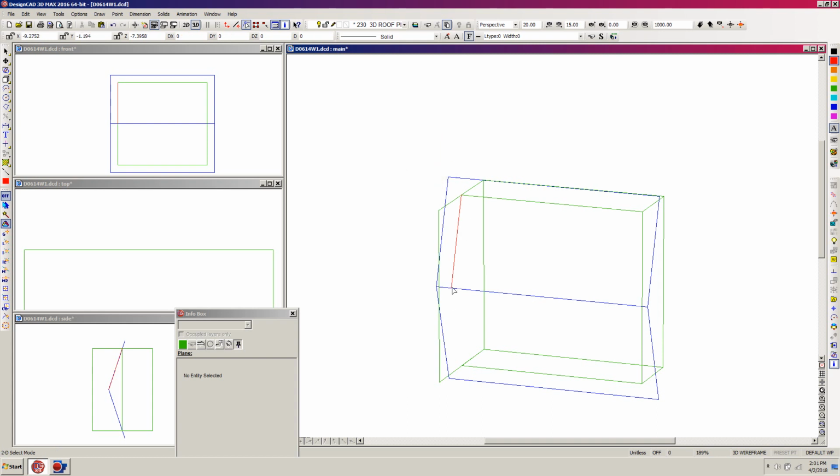It's the slope of the roof. And I'm going to do the same thing on the other side. So surface intersection, click on that, click just near the one and near the other, and you can see that it's done it again. So now I'm going to click on my wall, and I'm going to set a point right here at its former corner, at the corner where it used to be, and just click on that line somewhere, and then right click near the top of the wall there, and it snaps and puts a point there.